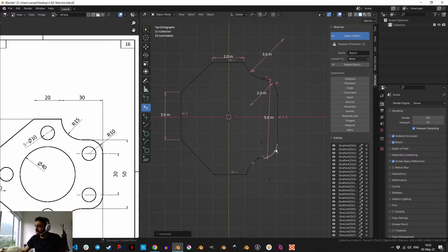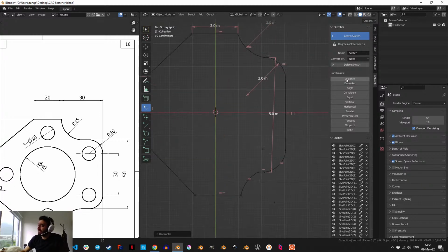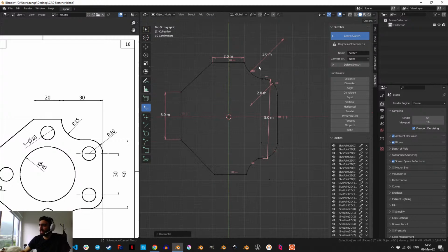To do this, I've found that in this implementation, the distance constraint is always between 2 points, and it cannot measure vertical or horizontal distances. It will always be at the exact angle defined by the 2 points.